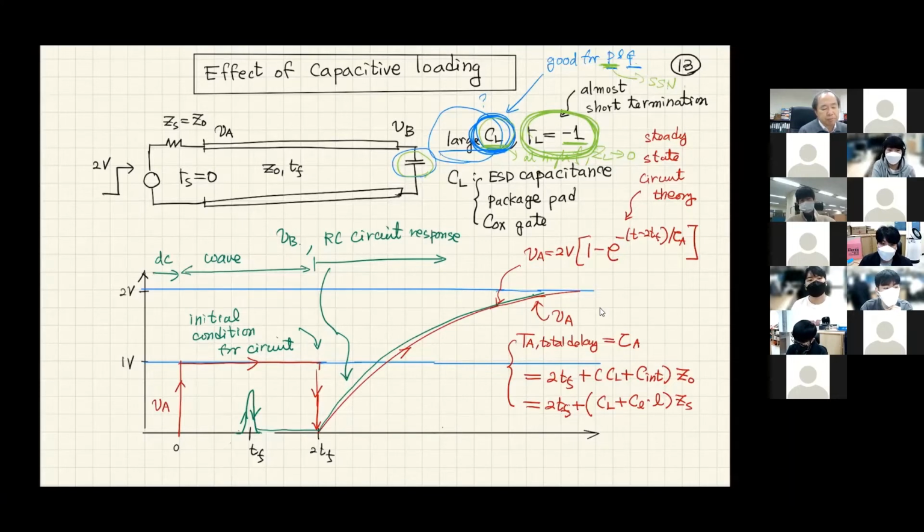As I mentioned many times, the level of difficulty of signaling design is 1, but power design is maybe level 3, and ground maybe level 10. That is because of the reflection coefficient of -1 of the capacitance. But let's forget about power and ground at this moment. So we're going to have a reflection coefficient of almost -1 at high frequencies.